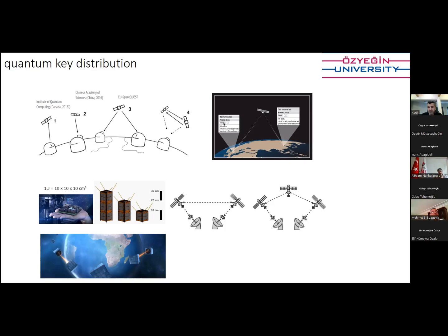But for CubeSat, it has very nice standards. You don't need to design specifically for anything. You just decide how many U you need. One U is 10 centimeter by 10 centimeter by 10 centimeter. You just put your payload inside, and like the power system, ADCS, the attitude determination and control system, the communication system, the pinch antenna, everything is inside, and then just like building Legos, you can make your own satellite, and it's very cost effective, very cheap.